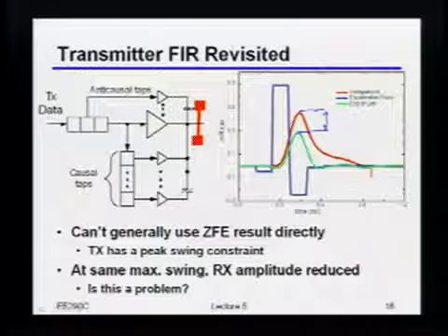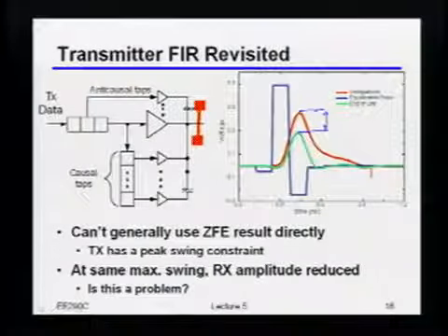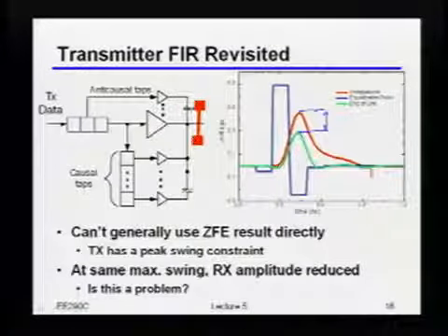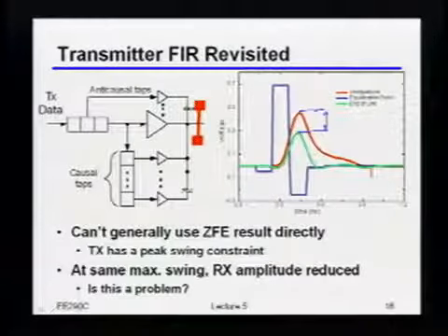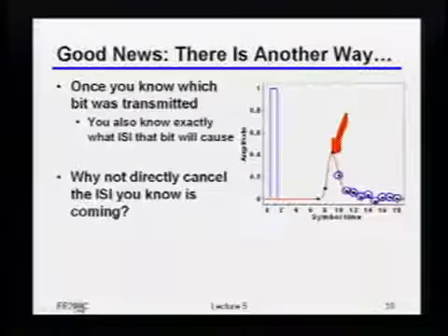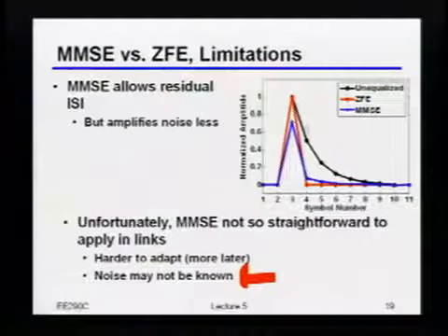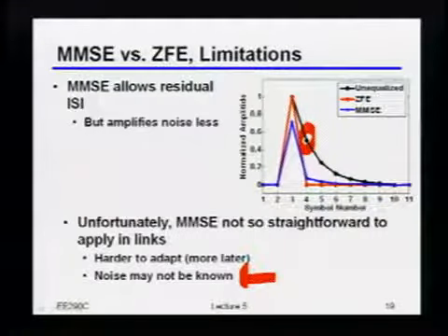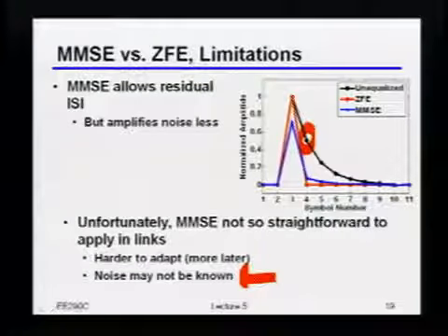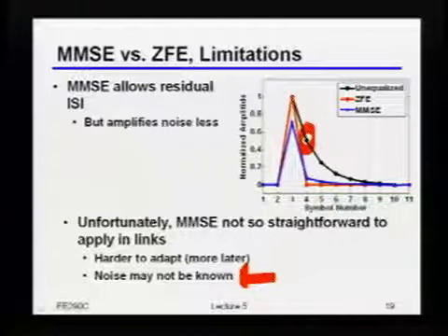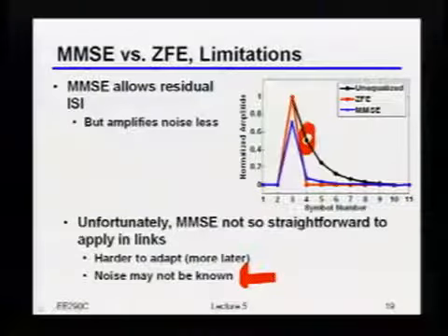These days, almost all of them, if they have a DFE, they're covering the things close by you, and then maybe they're covering things later on. There are also optimizations that people do the other way, which is they may use the DFE to cancel only that one tap afterwards, and then let the linear equalizer take care of everything else after it. The advantage of doing that is that now your linear equalizer is dealing with lower bandwidth signals. So that's a great question.